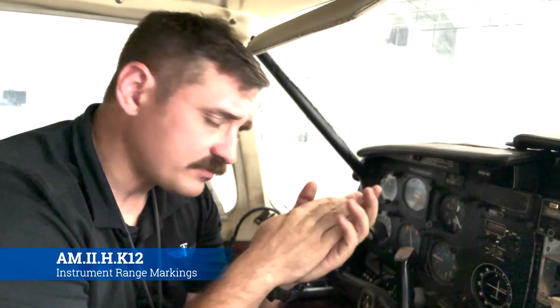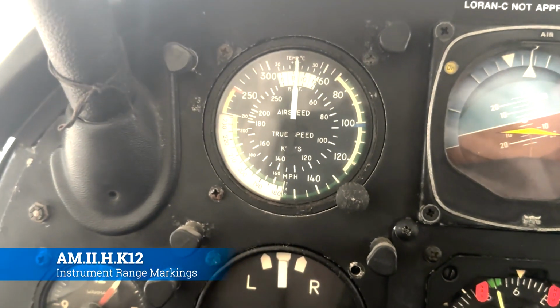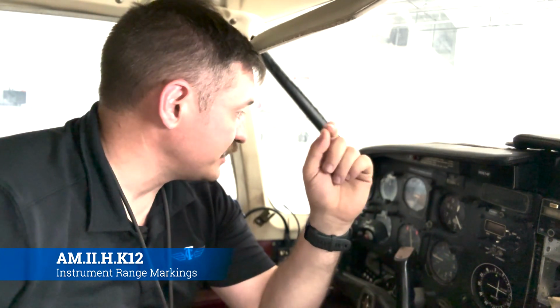All right. Now on that indicator, there is a white arc. That white arc will tell you when you can operate the flaps. Now, flaps have a range, just like anything else. If the plane is going too fast, you could cause structural damage to the flaps of the airplane. On this particular airplane, the flaps are cut off at, it looks like, 70 knots. So at 70 knots, you don't want to operate flaps below that, likely because the stall speed is probably right about there, and the airplane simply won't fly any slower than that.